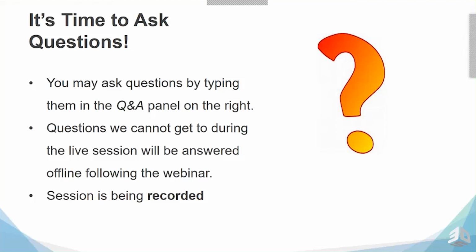Okay. I think this is probably the last question on orientation, but it came in during the examples with the cube, and it should be asked, why wouldn't we build this part by laying it down on its side? Or maybe we were just looking at different examples. Yeah, so that would definitely be the way that you would orient it for least deformation. But you probably necessitate a wire EDM to have that part removed from the plate.